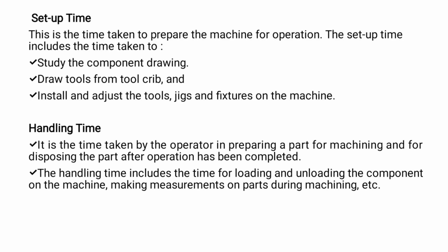It is the initial one. The setup time includes the time for studying the component drawing, tools for tool grip, installing and adjusting the tools, alignment, jigs and fixtures on the machine. Second is handling time. It is the time taken by the operator in preparing a part for machining and for depositing the part after the operation has been completed.